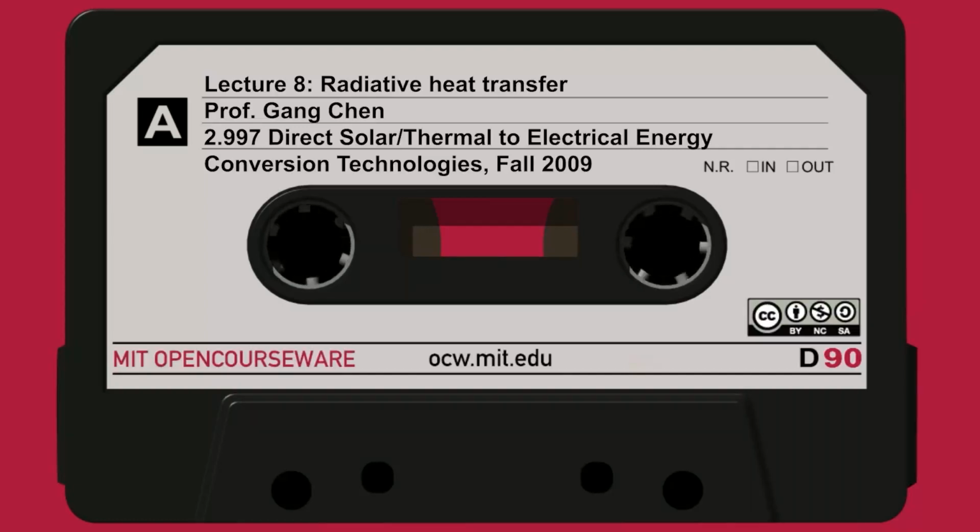And now there's another key concept. When I have an emitter, a radiator, how much of my radiation gets to you? That's the concept of view factor. If I have one surface here and another surface here, the view factor is defined as the power leaving this surface, that's the total power leaving this surface, and intercepted by the other surface.